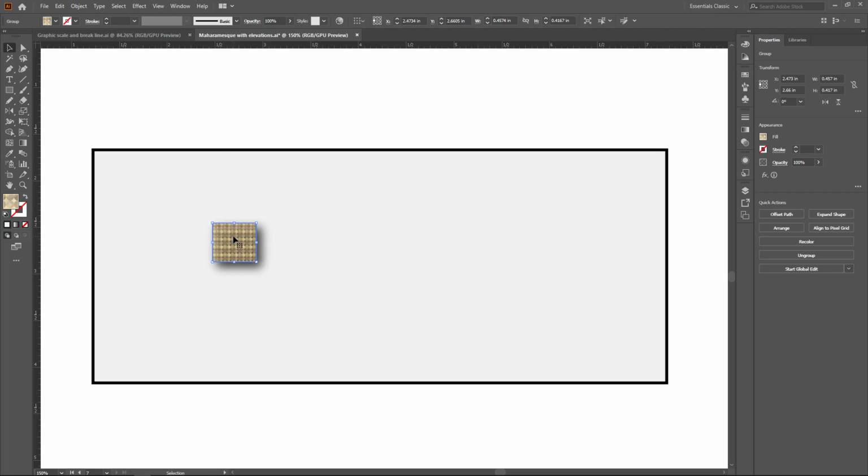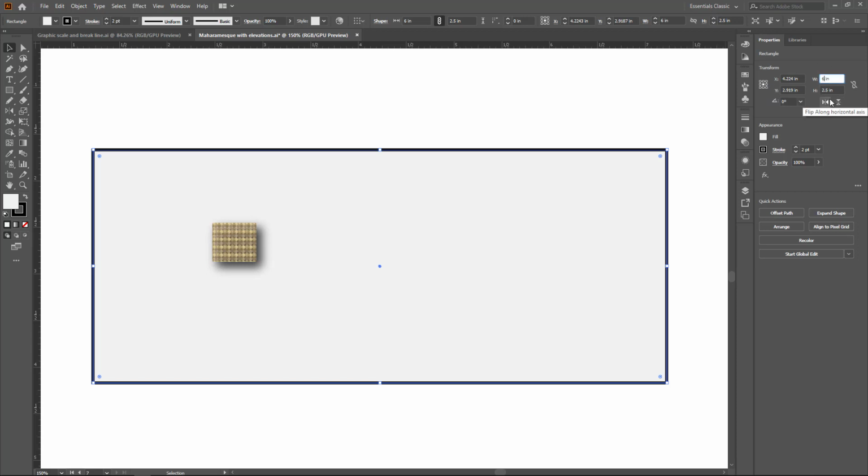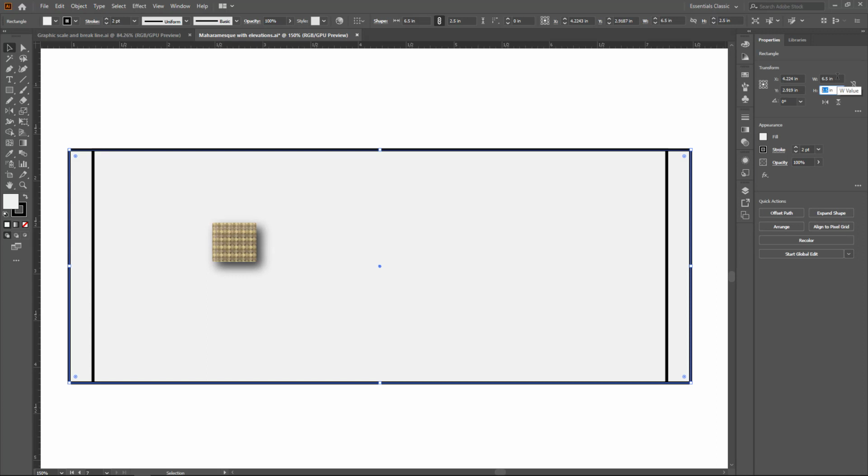But you can see an ottoman in plan is probably a square. It probably has a drop shadow on it. Now, how can I make this look a little more like a floor plan? Well, I can take this exact same rectangle and I'm going to copy and paste it in place. So I've made my copy, placed it behind the original. I can change the size of the object here based on my knowledge of scale, which is I want to make 6-inch walls. So I'll just add 1/4 of an inch onto either side of the object here.